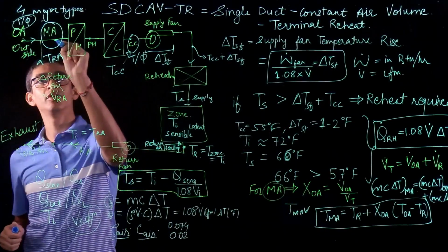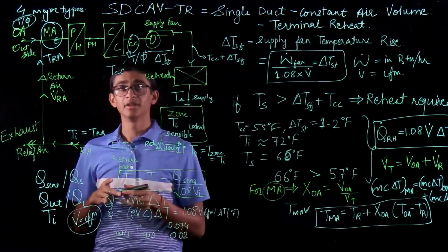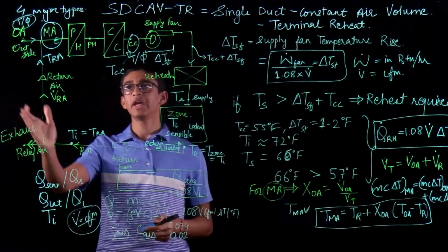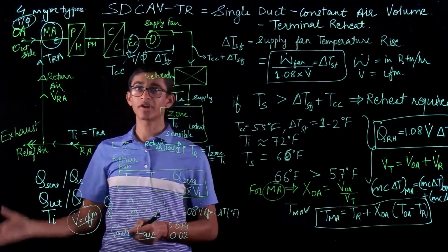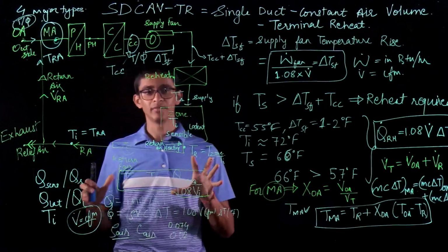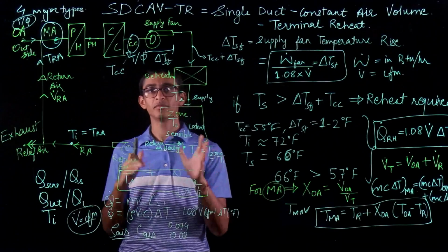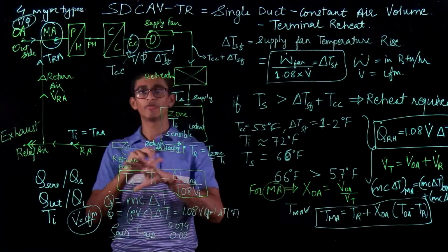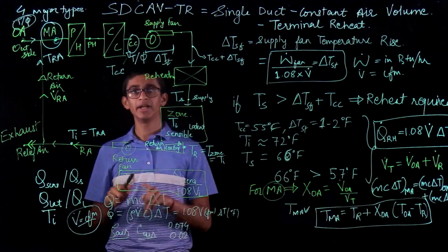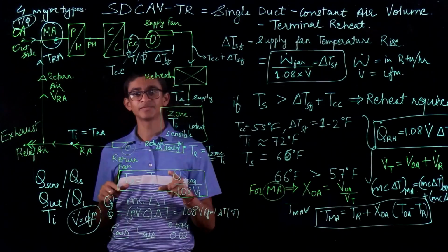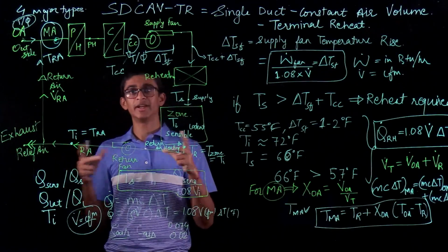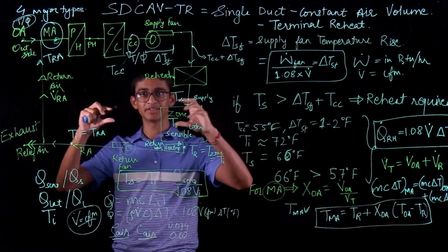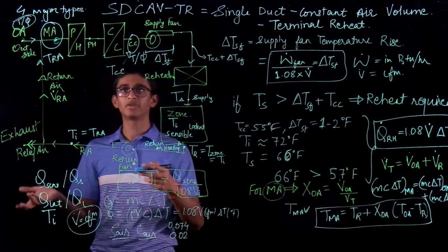So we have this temperature of mixed air calculated now. Now the preheater coil is for the purpose of not letting the cooling coils have a very cool temperature. If the air goes in which is already very cool, then the cooling coils might freeze up. Might freeze means it can go below 32 degree Fahrenheit or below 0 degree Celsius, and it will ice. All the water inside my coils can ice up, and I'll have all frozen, all packed, all solid, and that will lead to cracking, that will lead to bursting of the coils, because as the water cools, the density of the water reduces, and because of that the water expands. As the water inside the coils of my cooling coil expands, it will obviously lead to the cracking of the coils, right?